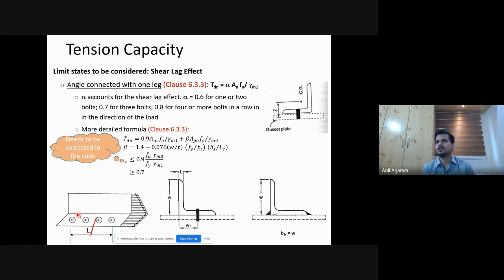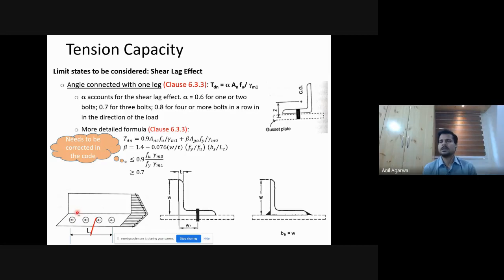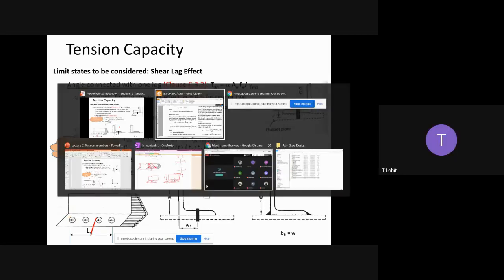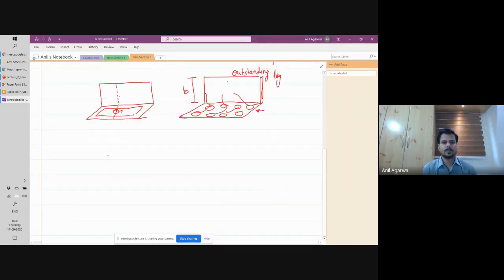0.0012 if it's mild steel. Yes, sir. Right? Let's say like 0.002. So 0.002 versus 0.2. What is the ratio of this strain, yield strain versus rupture strain? Rupture strain is how many times the yield strain? Just 100 times the yield. Yes. 100 times.